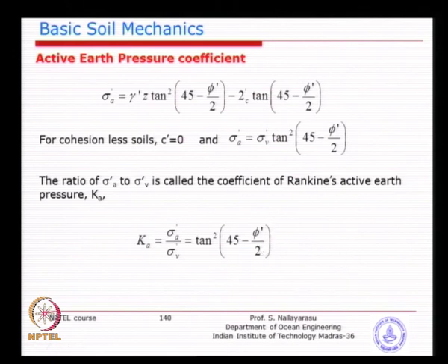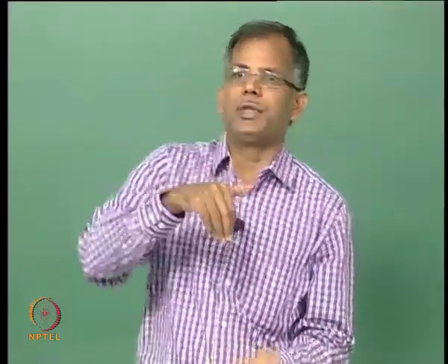So, what we are trying to derive is, when you apply some stress in the vertical direction, what will be the induced stress on the soil in that vicinity in the horizontal direction. That is what we are trying to find. It is easy to understand. For example, when you open up a hole in the soil and apply the loading due to the foundation coming from the superstructure, what happens to the vicinity? The soil is getting squeezed laterally because it is an infinite, semi-infinite soil medium.